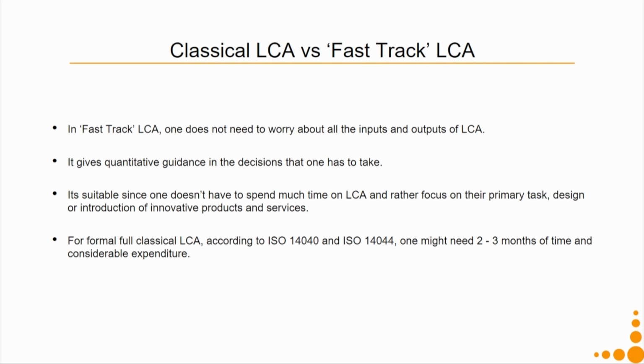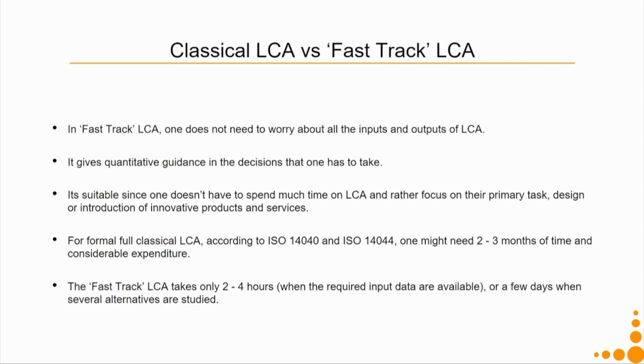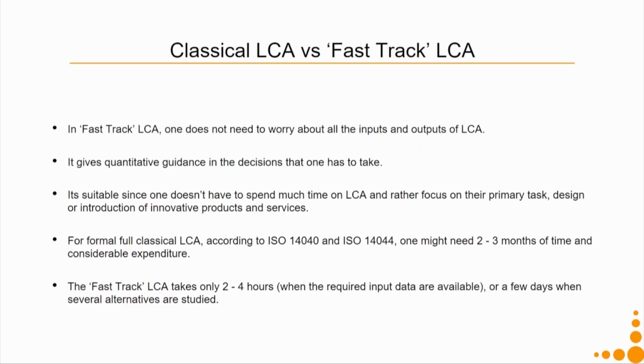The formal or full classical LCA, when conducted according to ISO 14040 and 14044, might take something between 2 to 3 months and considerable expenditure as well. The fast track LCA is also supposed to be conducted as per the rules of ISO 14040 and 14044, but it takes about 2 to 4 hours when the required input data are available, of course, or a few days when several alternatives are to be studied.